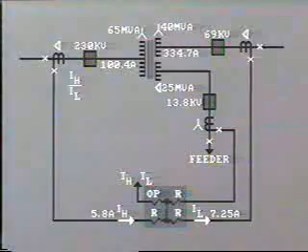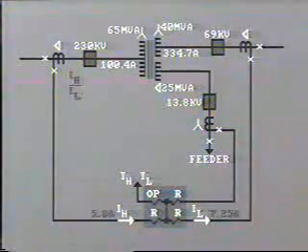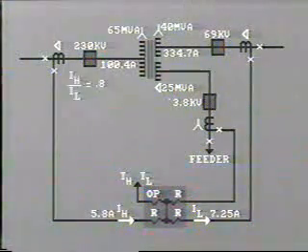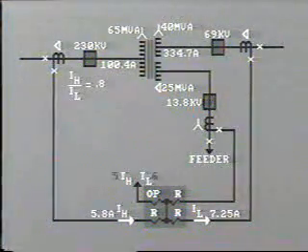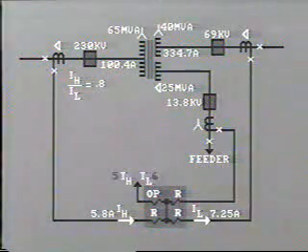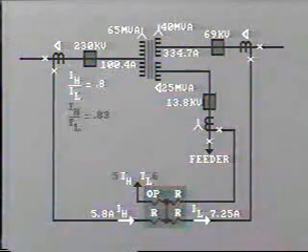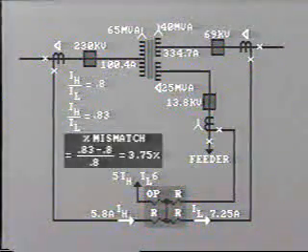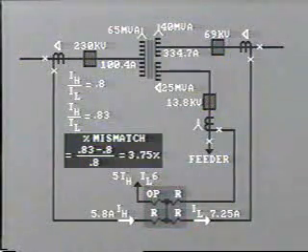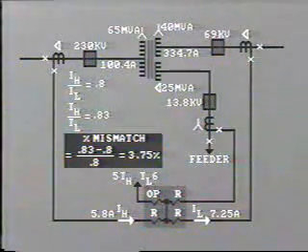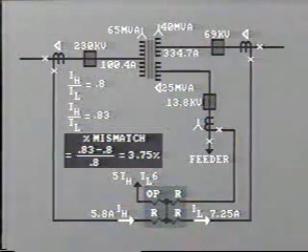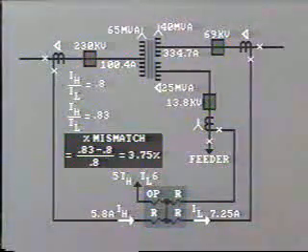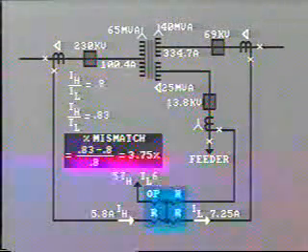The ratio then between IH and IL equals 5.8 divided by 7.25, or 0.8. Now, let's suppose that our taps are set on 5 and 6 respectively, giving us a tap ratio of 0.83. Our mismatch can now be calculated as (0.83 minus 0.8) divided by 0.8, which equals 3.75%. This is well within the transformer differential relay restraint setting.